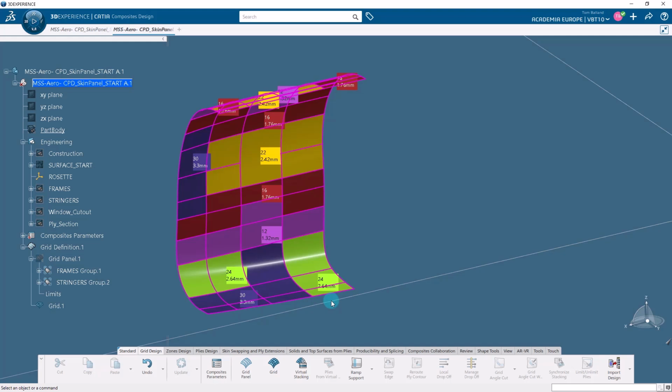You can manipulate the ply sequences by adding or removing the cells to or from a sequence, merging the plies into a single sequence, editing rows in the virtual stacking, changing the layup sequence, and importing stress information into the virtual stacking. You can modify the stack-up order, ply shape, and add or remove plies or sequences using this toolbar, if the part is being designed without the main stacking sequence.